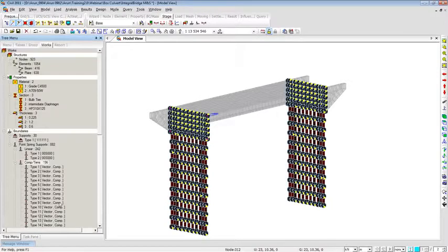If you want to compare the results, you can choose that approach also, or you can go in and modify the values. Basically, let's say you see that for some reason at the base of the pile some spring conditions or soil conditions cannot be replicated in the program.